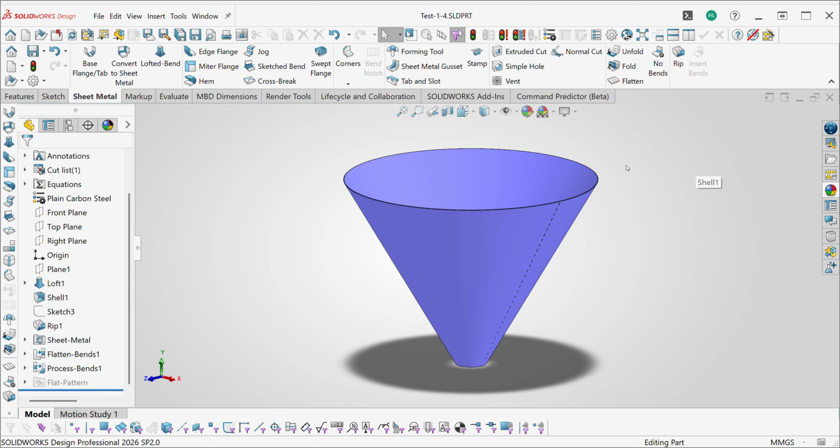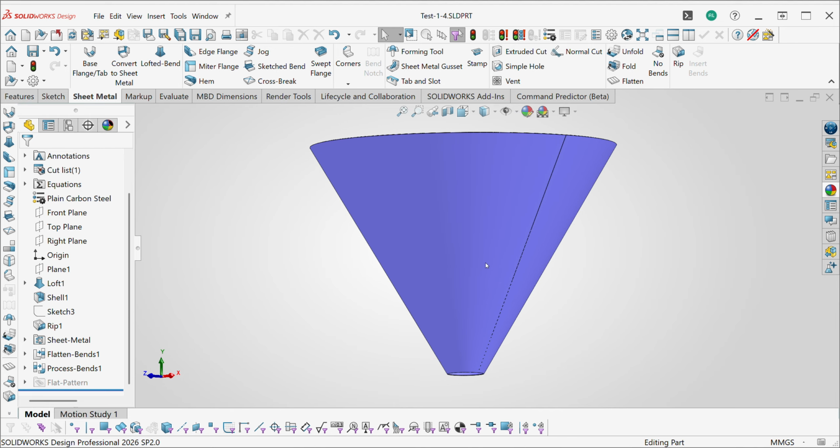Perfect. Let's quickly check how to convert a frustum from a shell part to sheet metal in SolidWorks. Application could be the bottom hopper in a 28-ton cement silo. First, we sketch the offset circles for the 2500 mm upper shell interface and 300 mm exit on two parallel planes spaced 1900 mm apart. Executing standard solid loft, then apply a 6 mm shell command, will hollow it out.